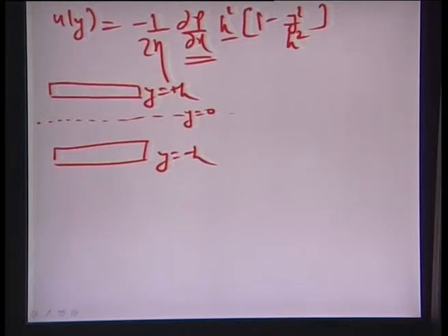If you plot u with respect to y, essentially you get a parabolic profile, the square on y. So, there is a flow velocity variation of this parabolic type, and this makes sense because the velocity very close to the channel wall is 0 on either side, and it is maximum somewhere at the center of the channel.